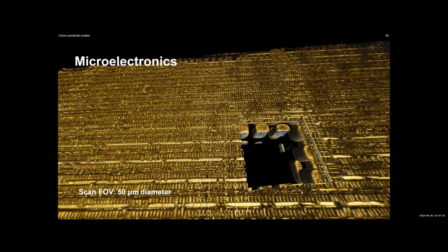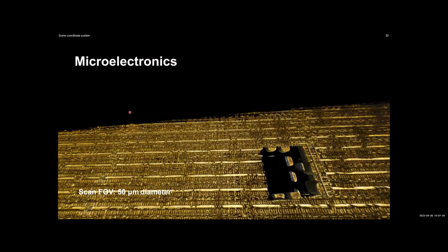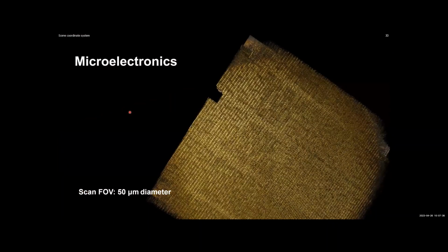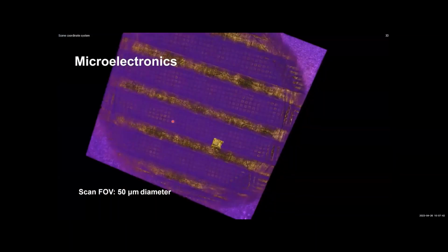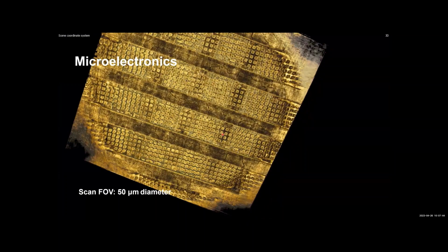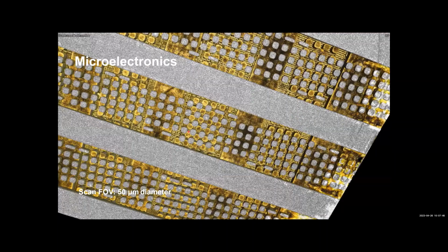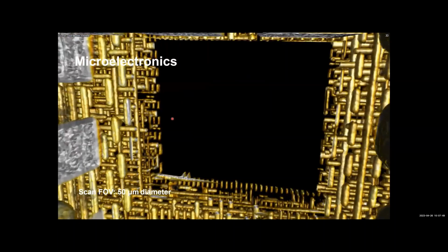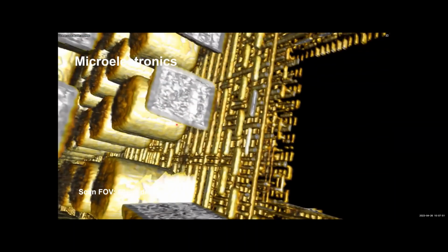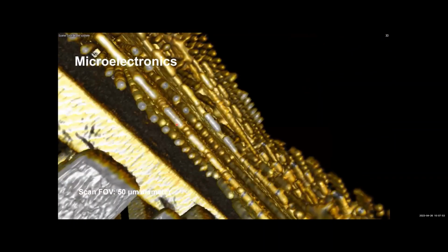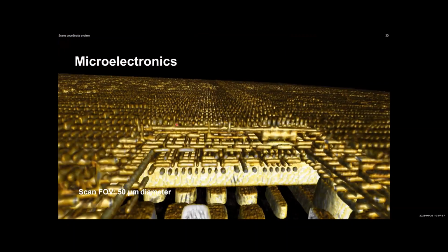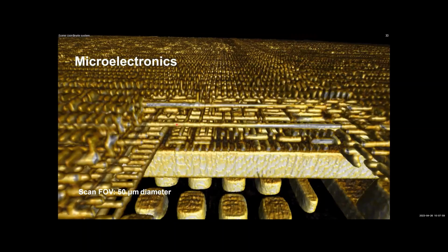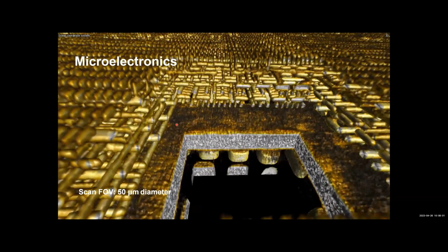If you look at microelectronic circuits, for example, this is a 16 nanometer IC on this image. Oops, I probably need to play the video again. You can image the full three-dimensional integrated circuit non-destructively, so you don't have to do it layer by layer. You put the entire object in the beam, you do tomography like you would do a CT scan, and you can have typically 20 nanometer resolution, but with a very large field of view.